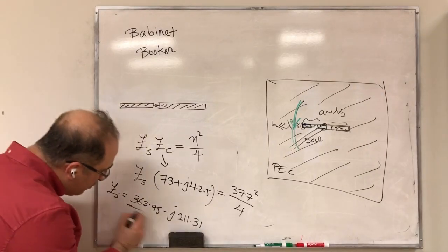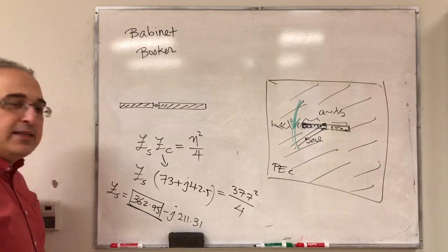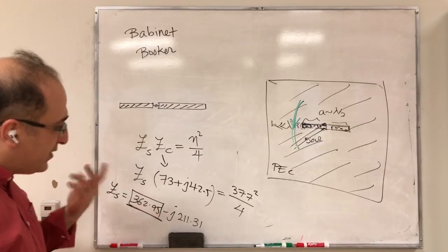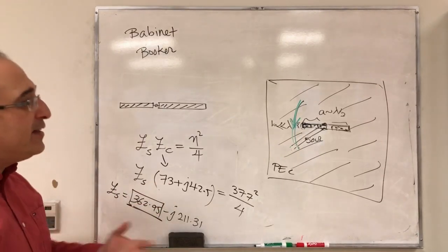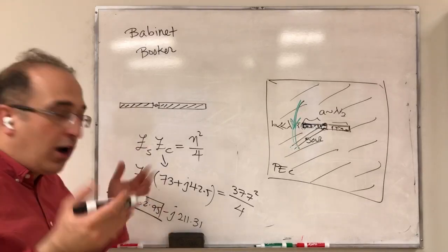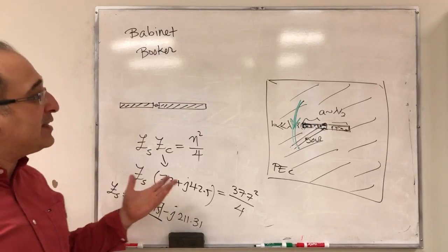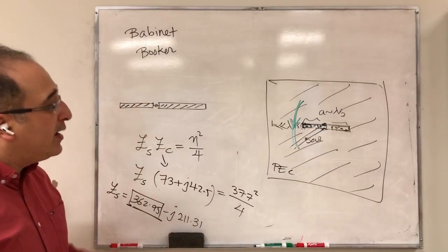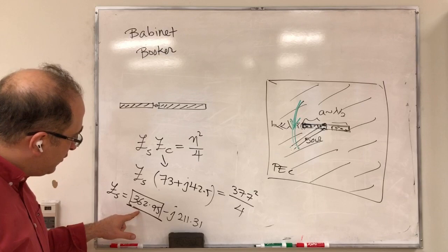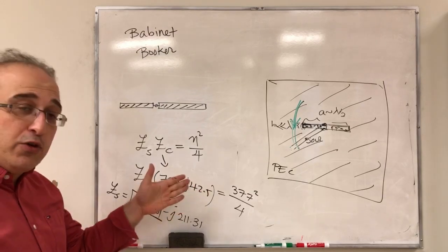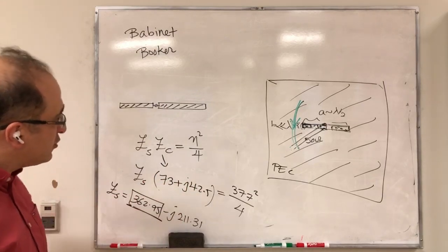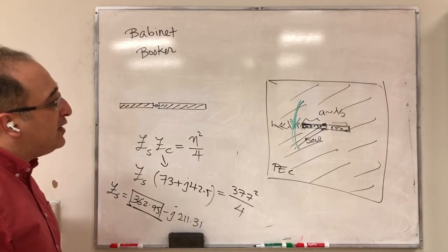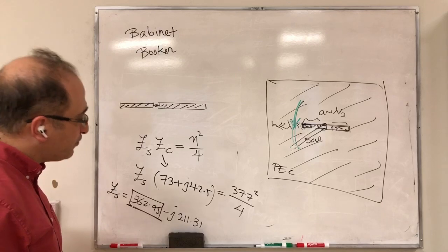And even if you just look at the real part of this, it's not appropriate to be matched to 50 ohm. If you are about 73, it's reasonable. But when you get to that, that means you are very high in terms of impedance. That's exactly what we predicted. We said here you should have a high impedance value. You will have that. So that's why you make it a little bit offset. So this actually shows you that that's not a good location to feed the slot antenna.